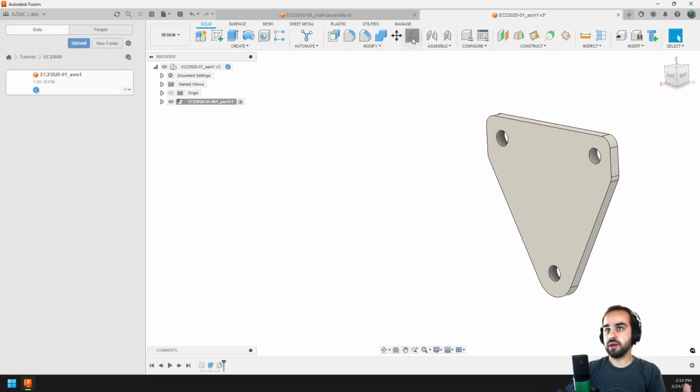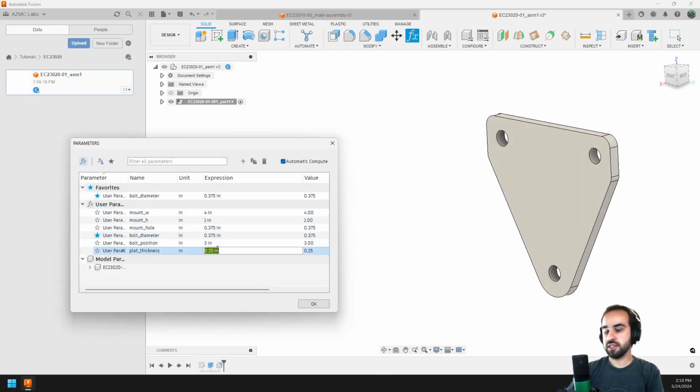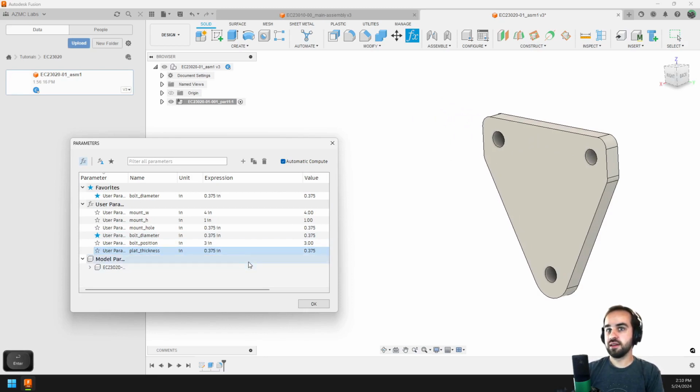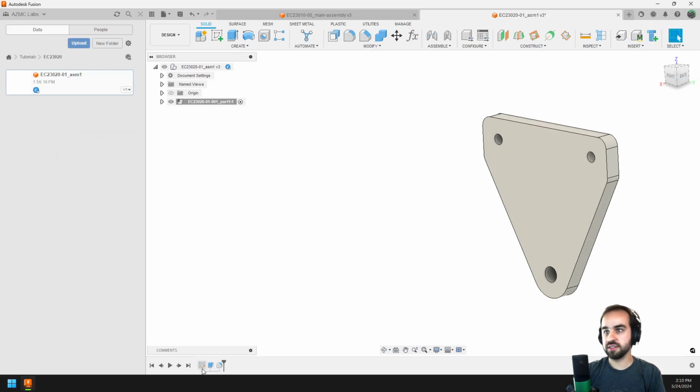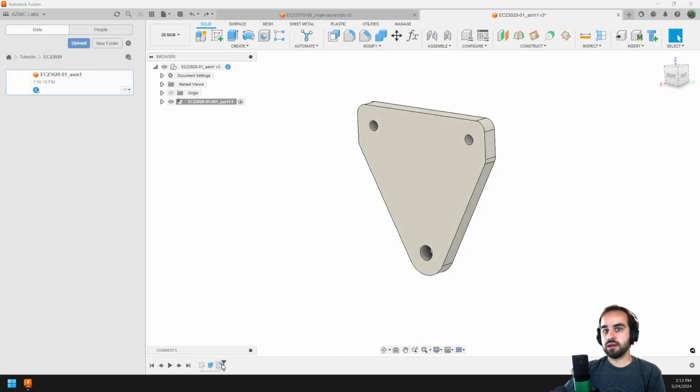And you can pull up the parameters from the 3D view as well, change different aspects to see how it updates. Even things that were only defined in the sketch, you can just update right from here. So you can see how this makes it very quick to go and change your file and update it without having to go locate where your sketch is on the timeline and reopen it. So now my part's done. I'll go ahead and group these and then reactivate my top level assembly.